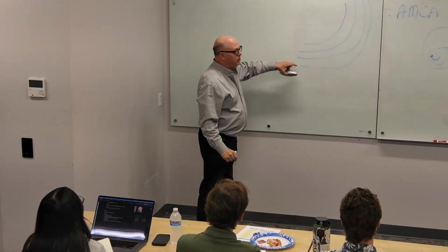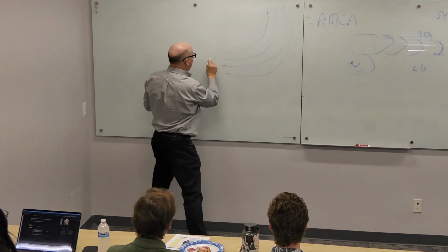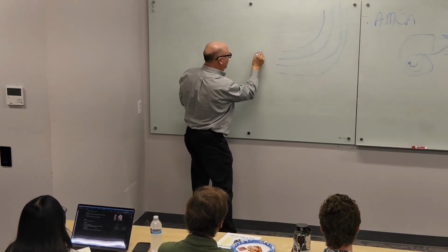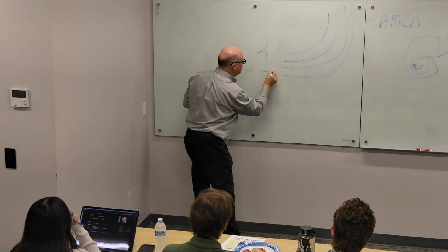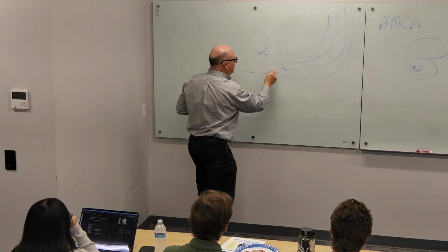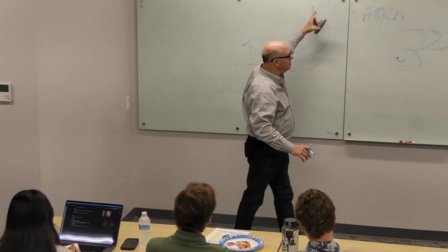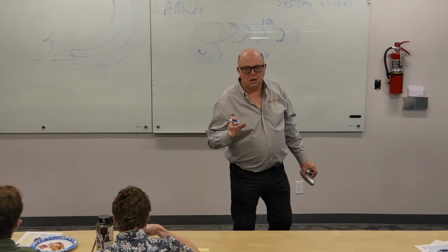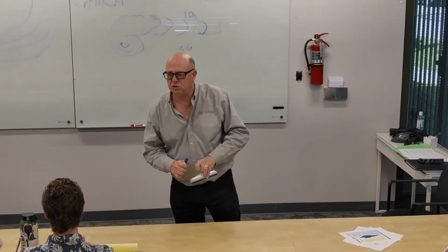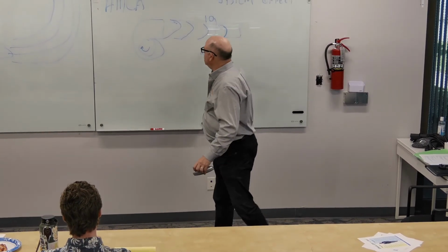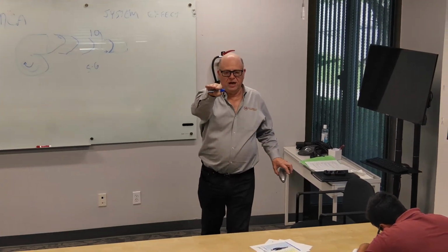Now we've got 2 splitters, and we have taken the benefit of this, and we've got this velocity profile coming off of our fan that looks something like this, right? But we've sliced it into 3 segments. And so what we've done is we've limited the amount of turbulence. This 10 diameters gives you as little impact on the velocity of the air as possible.